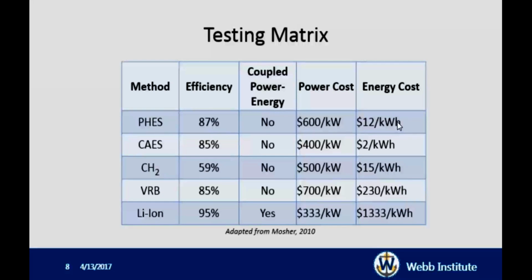But in that situation, flywheels are much better used for high power, short discharge time applications, whereas what I'm looking at is much longer discharge times over fixed power, on the order of hours or days as opposed to seconds or minutes. They are viable, they do work. There are a lot of flywheels actually in use right now, but they're for a different use case than what I considered.